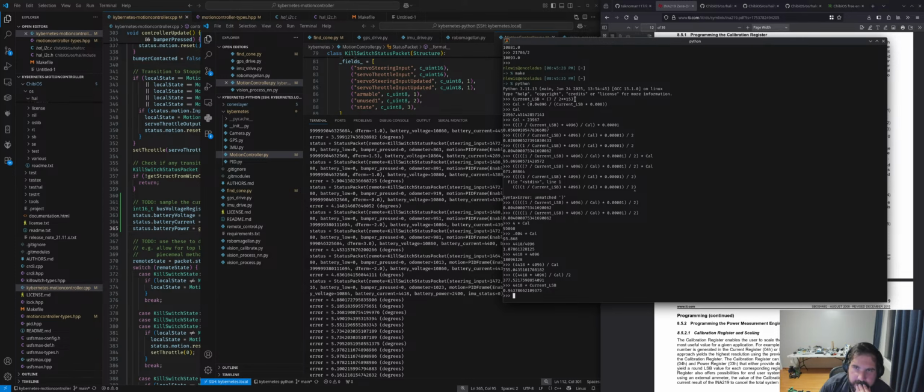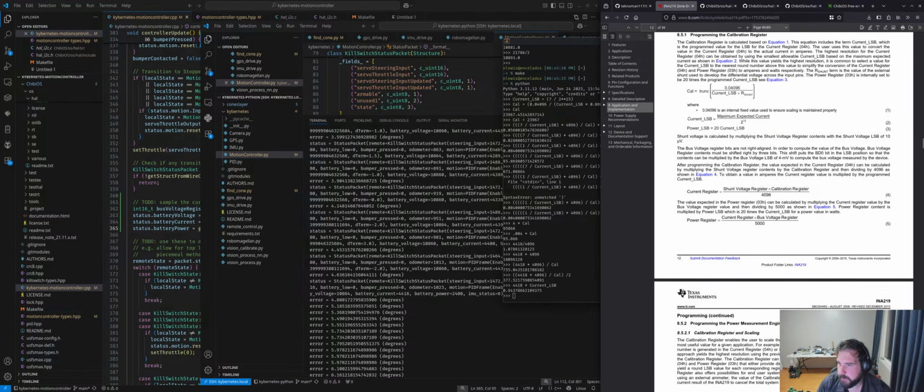Okay. So because we're trying to scale, right? As you said, Raphael, I don't know if this is actually what you're referring to, but the whole point of this entire thing was to map 7 amps to the full range of the amplifier. So if we've programmed that, then we want the least significant bits here to be, let me just multiply this by that range thing that we did. So it would be this divided by what it could be, converted to a range 0 to 1 and multiplied by the range that we programmed. All right, presumably.